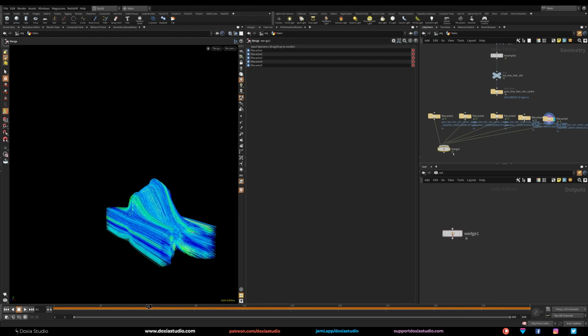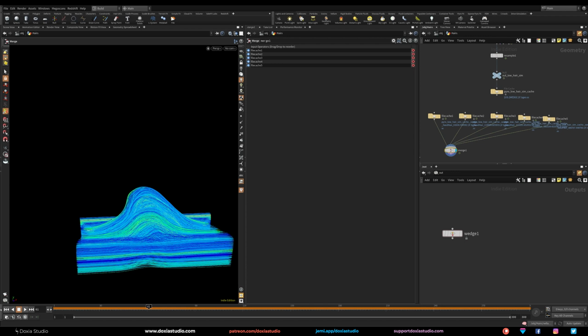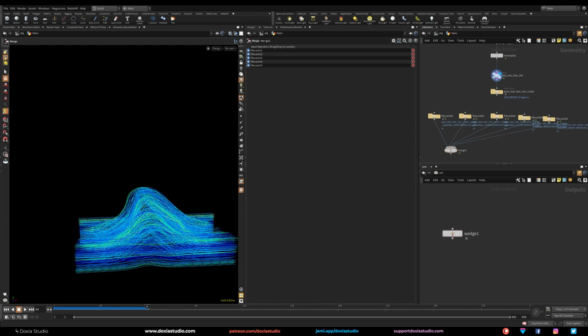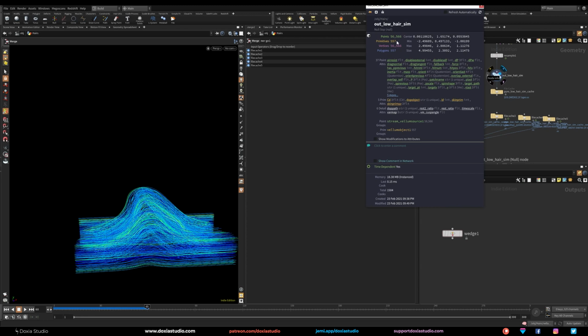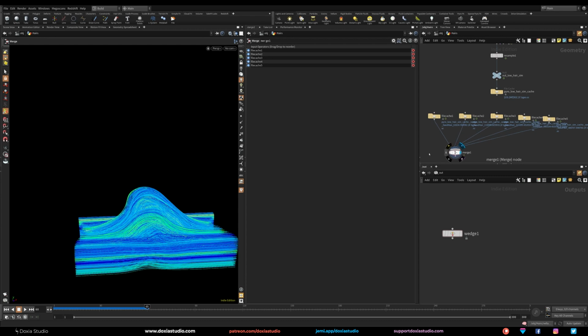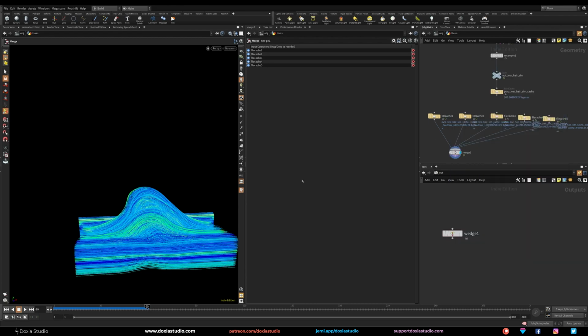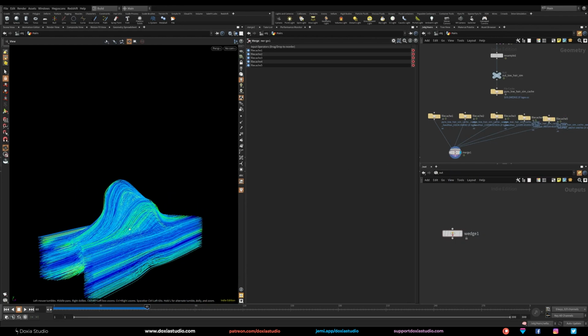So everything combined, you will see that. Let's go place a merge. We have now a more dense system, right? Instead of having, let's go cache to 60. Let's go here. So before we had 500, right? And I only ran this wedge 5 times, okay? So as you can see here, we had this with 500 primitives. And now with the wedge, really quickly, under 3 minutes, we have now 2,400 primitives, okay? So we have 2,000 hairs here.